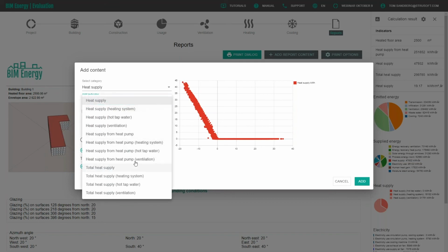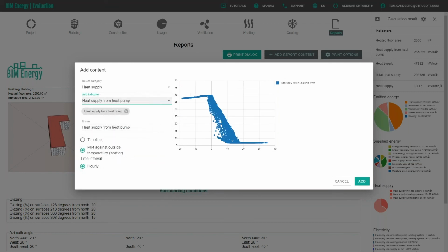And then we have the heat pump. And there we see the simulation of this heat pump, that it's supplying all the heat up until 0 approximately. And here it's working at its maximum capacity, and it will decrease a little bit as the cold side gets colder and the hot side gets hotter. So this is a good way to see, is the heat pump adequate? Is it big enough? Should I go and try another little bigger one or smaller one? And that, of course, depends on the prices for this electricity and the installation cost of the heat pump and how much this peak heating costs.